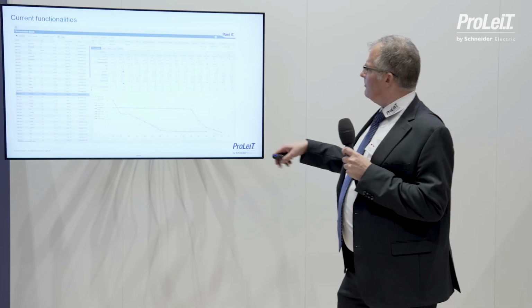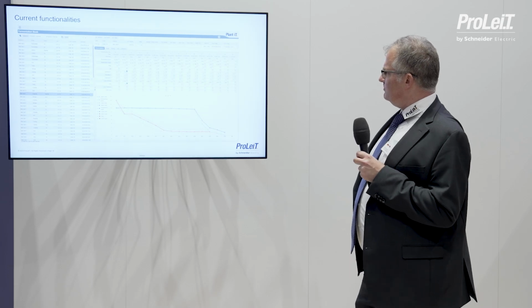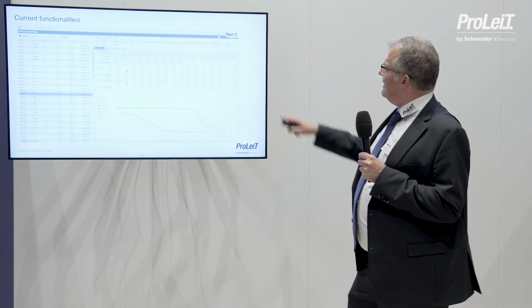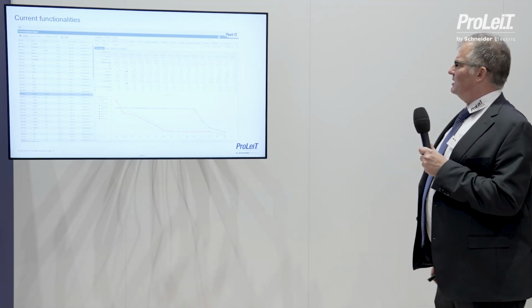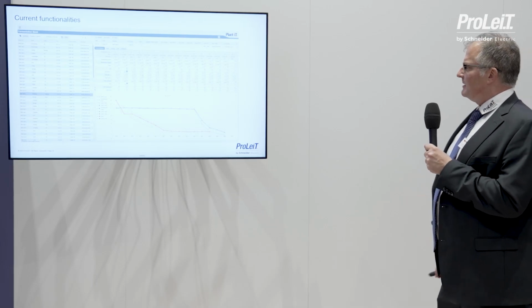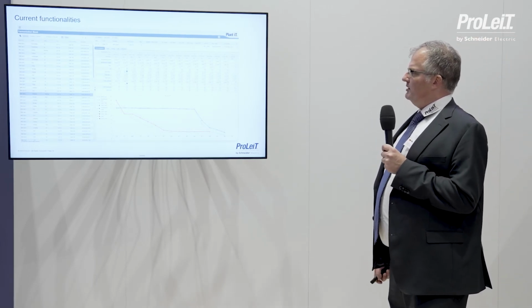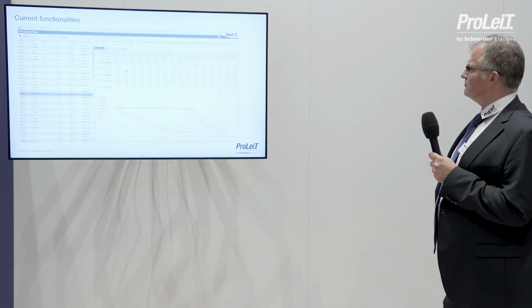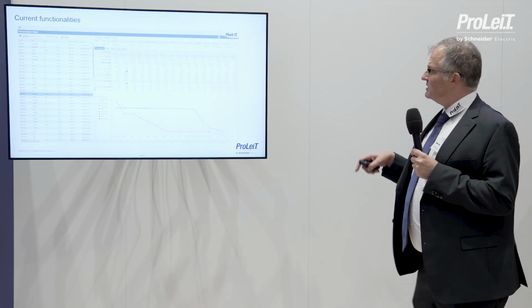So the normal way is to show, of course, the temperature and the degree of Plato. And here I can freely define what should be the upper and lower limit on the different days where we have parameterized it. We have a total fermentation time of 15 days, but depending on the beer type, depending on the brewery, this can be changed individually. So if you have beer types of fermenters where you have a fermentation time of 20 days or 25 days, we just can change it.